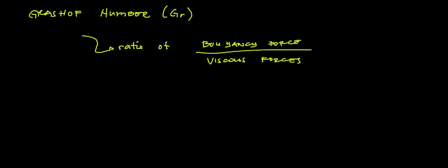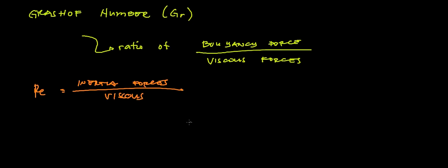And if we recall the Re, our Reynolds number, it is actually the ratio of what? The inertia forces to viscous forces as well. Okay, so if you notice, the Reynolds number is the one applicable to forced convection, right?